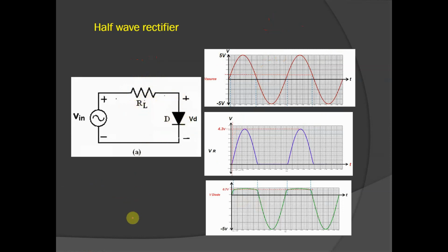Now look at the voltage across the diode. Here, we are monitoring the voltage across the diode. If we want to measure, this is our oscilloscope. Our source is from the function generator. This is our oscilloscope, channel 1, channel 2. Of course, channel 1 here. Here I will connect it, this one here, sorry. This is the ground, considered as the ground. This is the red of the oscilloscope. This is the black of the oscilloscope, of the source. Okay, so now this is channel 1.